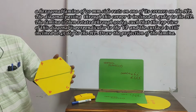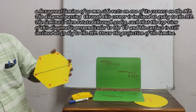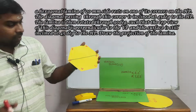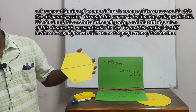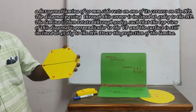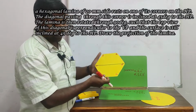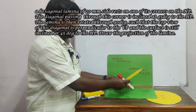A hexagonal lamina of 20 mm side rests on one of its corners in the HP. Okay, any one of these corners in the HP. Let us check which corner is going to lie on the HP after reading some other details from the problem. The diagonal passing through its corner is inclined at 45 degrees to the HP. So the diagonal is passing through these corners only, and these corners are making a 45 degree inclination to the HP. So it will be like this.